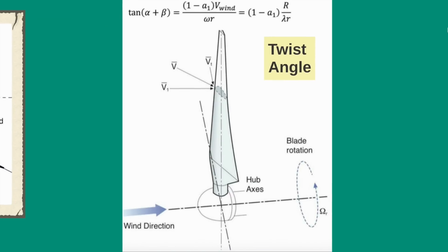The rotational velocity is not constant around the blade, therefore the effective angle of attack varies. For it to be optimum at each point along the blade, the angle of pitch has to change, requiring a higher twist at the root because of the lower velocity, and lower at the tip. The pitch angle was calculated through the formula shown, which is derived from trigonometry.